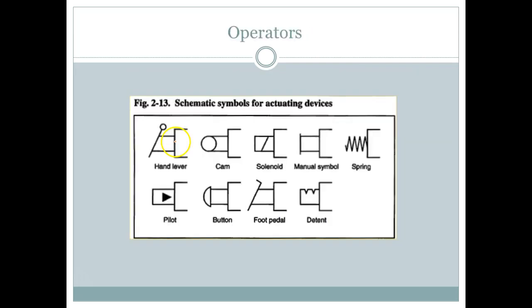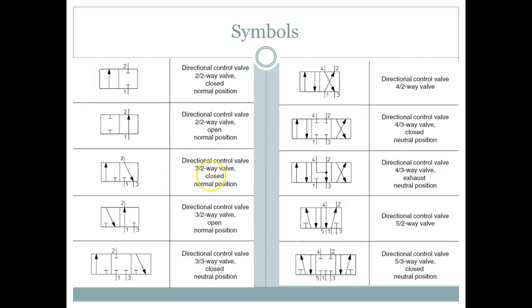So that's one of the biggest differences, guys. Here, basically, we ask you what that center does. We don't ask you the name because we have so many different names, right? You understand? But when we have a 3-position valve, where is the normal position or at-rest position? It's going to be in the middle, right? If we have a 2-position valve, where's it going to be? To one side, depending on where you put your actuators, right? So we still have what we call a normal position or reset position.